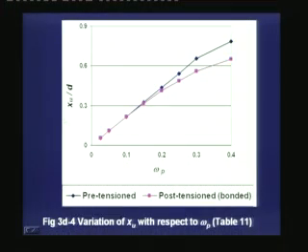On the other hand, if we try to understand the variation of the depth of the neutral axis, then as the amount of steel is increased, or as omega p is increased, the depth of the neutral axis also increases, because if we have more and more steel, we need more and more concrete to balance the force in the steel. Thus, the values given in the table, although they are approximate, follow our intuition of the behavior of prestressed concrete members.